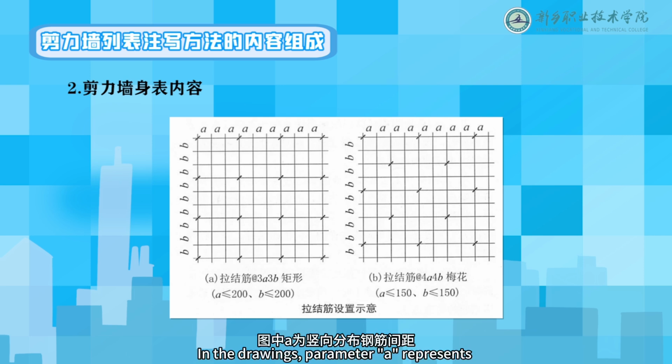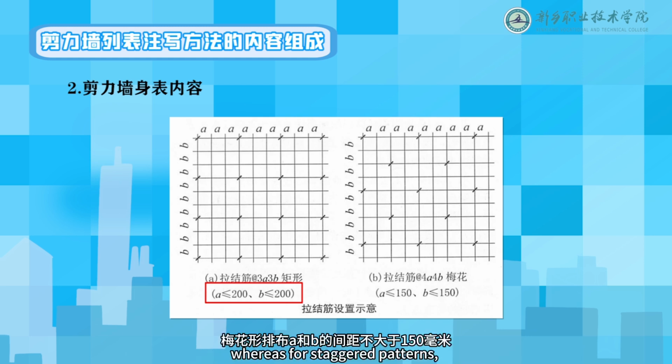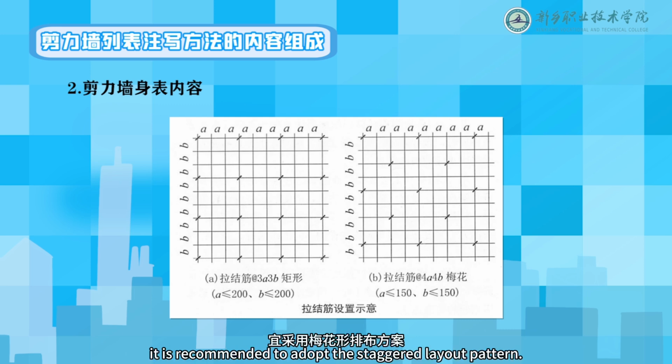In the drawings, parameter A represents the spacing of vertical distribution bars, while B denotes the spacing of horizontal distribution bars. For rectangular arrangement, the spacing of A and B shall not exceed 200 mm. Whereas for staggered patterns, the spacing of A and B shall not exceed 150 mm. The spacing of tie bars in both horizontal and vertical directions shall not exceed 600 mm. When the construction drawings do not explicitly specify, it is recommended to adopt the staggered layout pattern.